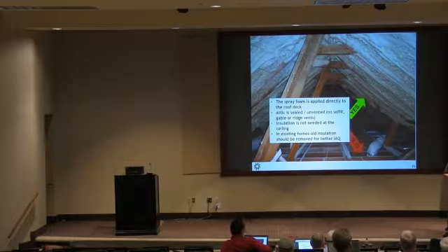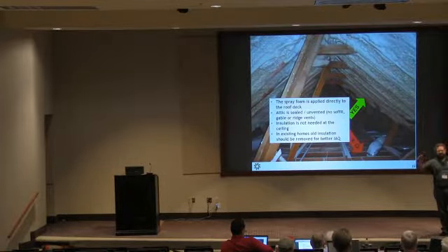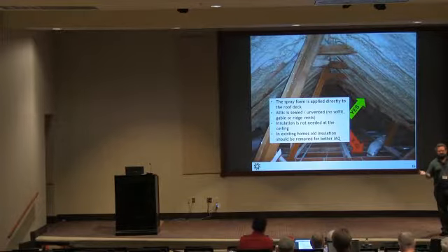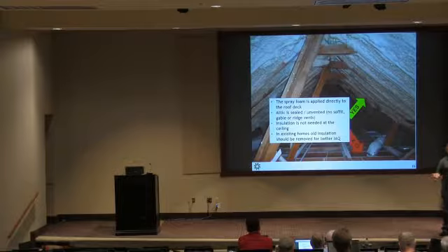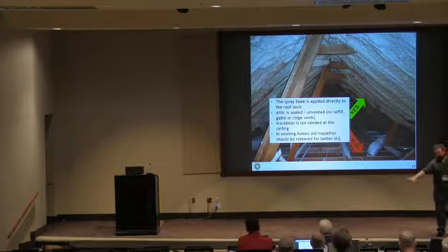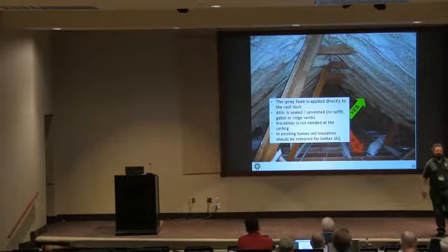Because what you saw is an example of someone spending money on something that has very little value. And that's not to say it wouldn't air seal and add insulation, but why in the world would you apply that product in that way when, for probably only slightly more coverage, you could seal the attic assembly and reduce the air temperature up there? I guess I could say if they didn't have equipment up there, they could foam the roof surface and that would be fine.